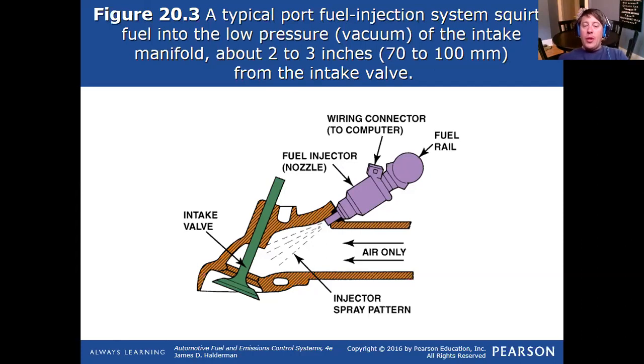Well, sometimes you'd have a valve that was open. Sometimes it would spray against a closed valve. The engine was running at 1,000 or 2,000 RPM, so the fuel didn't really have a chance to cool up on the backside of the valve, even though technically it did. But in the early days, we didn't fire sequentially. If you're working on a vehicle from like the mid 90s to current that has port fuel injection, it's going to be sequentially firing that fuel.